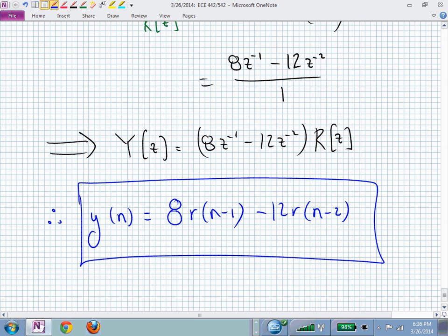There's our governing relationship, difference equation. It's no longer a differential equation. We're in discrete time. This is our linear difference equation relationship between our reference input and our output y. And what if we apply a constant? What if we say our reference is 1, a step? Let's see what y does.